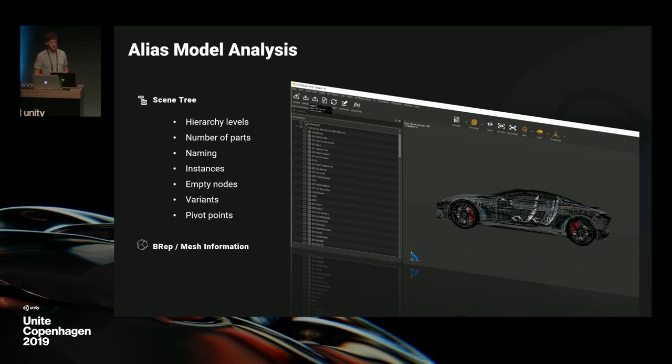Now, regarding the CAD geometry data, in our model, we need to look if parts are geometrically linked or disconnected, and see if it makes sense for a good visualization. So, in our case, we have only surface CAD data, and many parts are attached together. So we'll need to detach them in order to create logical groups like the left door, the right door, the front wheel, the steering wheel, etc.